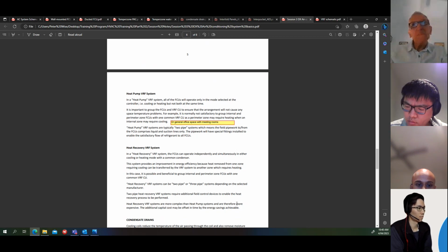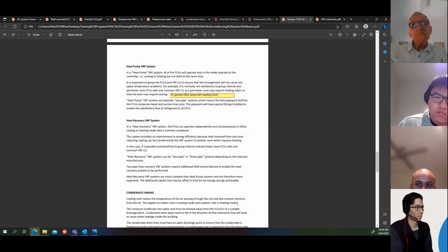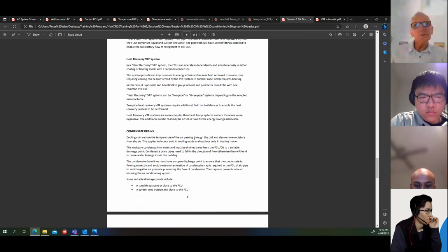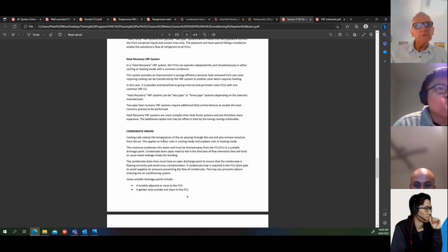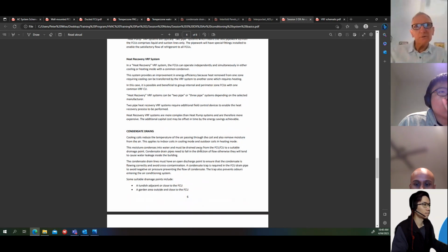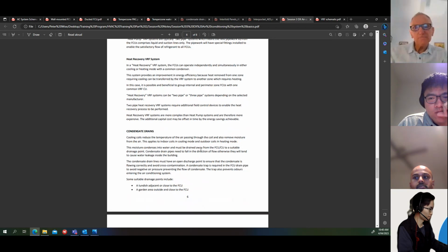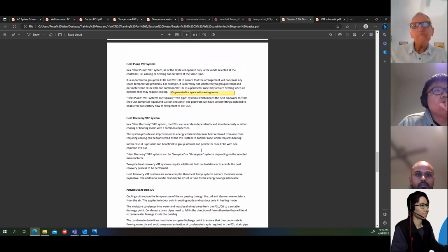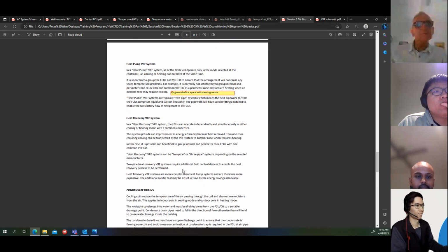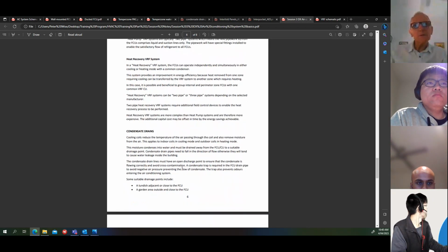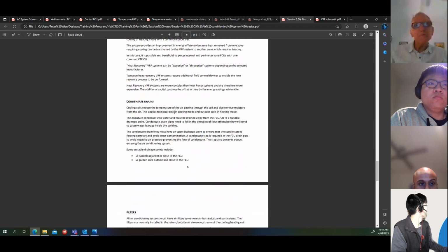I just want to mention condensate drains. Cooling coils reduce the temperature of the air passing through the coil and also remove, oh, sorry, before I go on, any questions on VRF or VRV? All good? Okay. Condensate drains. So when you're reducing the temperature of the air passing through the coil, you're also dehumidifying the air and removing moisture. So this applies to indoor coils in cooling mode and outdoor coils in the heating mode.